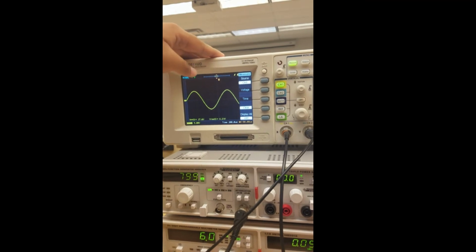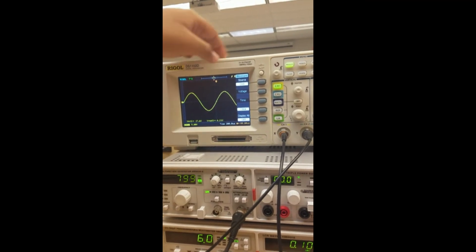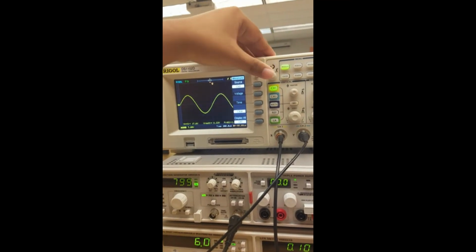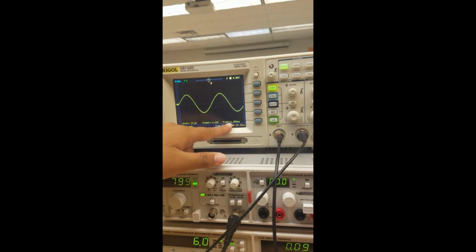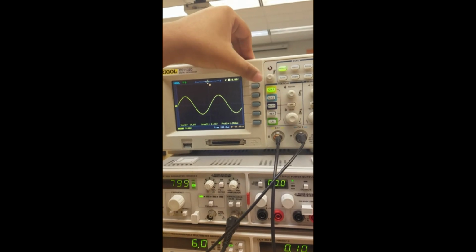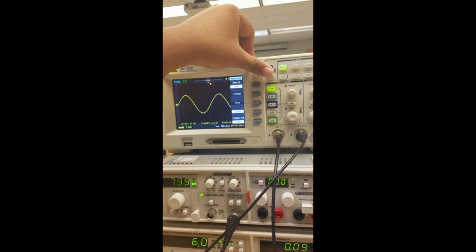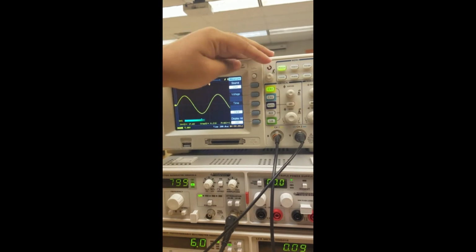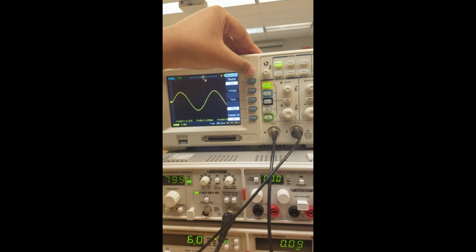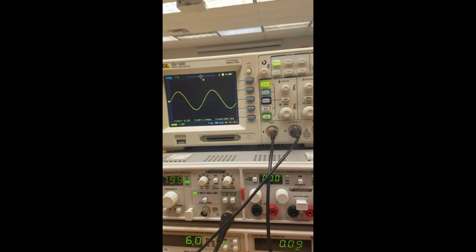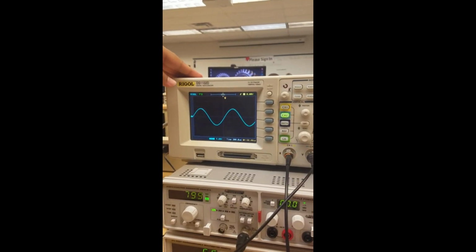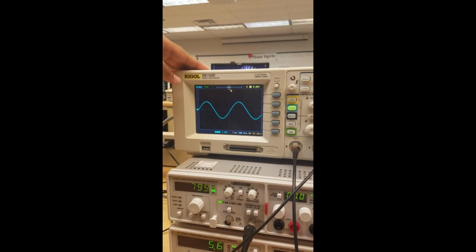Now to measure period and frequency, you want to go to time. So you want to click here. Period would be 1.2 around this area, and then we go back to time, go to frequency. Here we go, and that's how you would measure for channel 1. Channel 2, it's using the new way. And the same thing as channel 1.